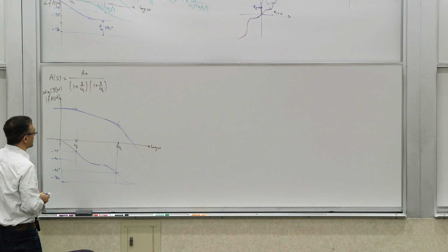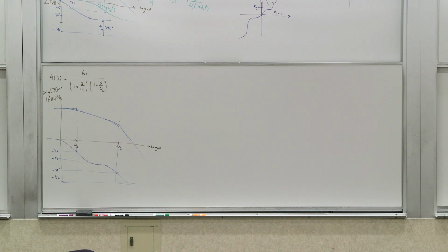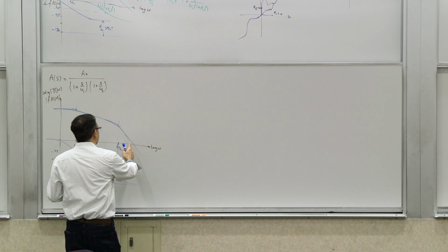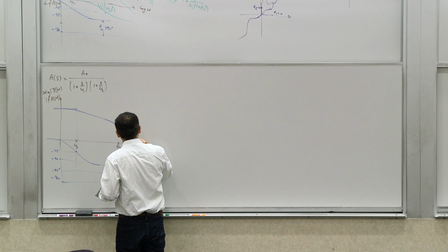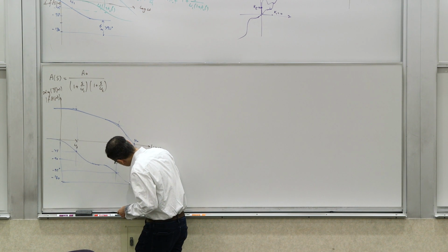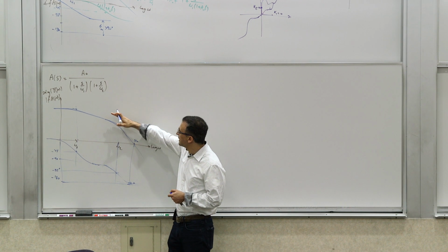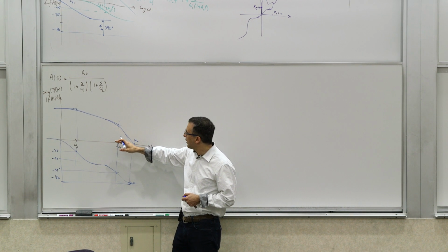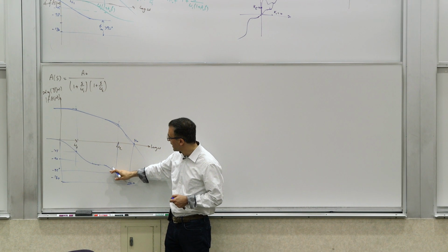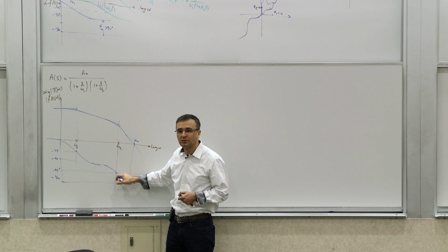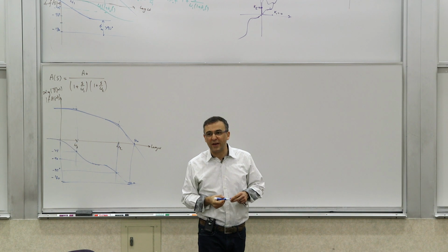So that's how it looks. So what is our phase margin? Well, it depends on where we really hit the gain of 1. If this is omega unity, then the phase margin is this much. If this whole thing was scaled down and our omega unity were here, for example, this would be our phase margin from a phase margin perspective.